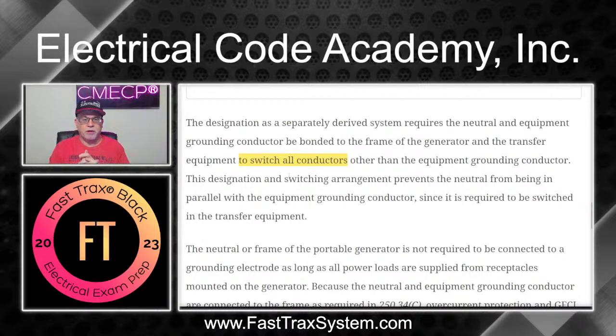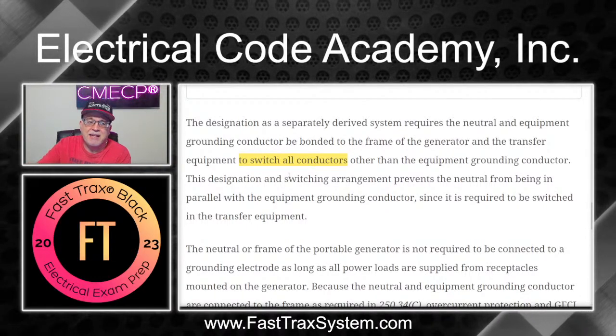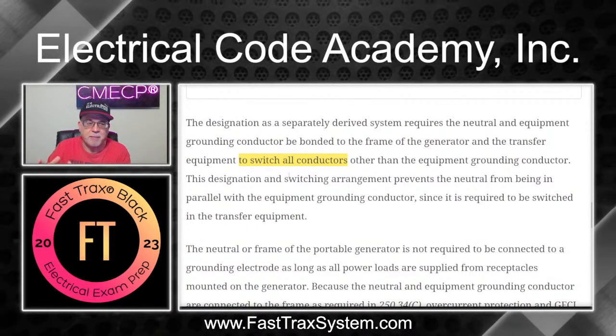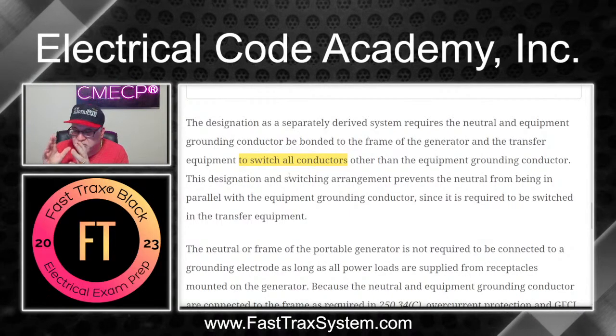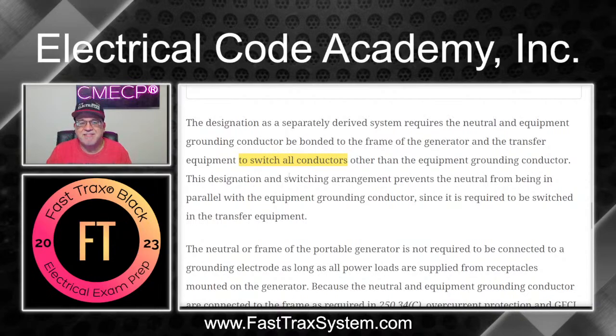That is so important. So if I use a portable generator, and I just go buy a bonded generator, that's a separately derived system, and I go install it at my house, okay? Now what I've got is what? I've got a transfer switch.